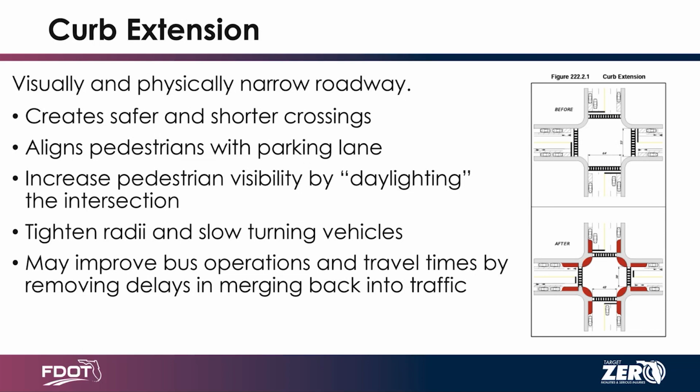And then you're also looking at some of the requirements in the MUTCD around all-red times, making sure that you're accommodating, especially when there's a bicycle signal. But if you think about it, if bicycles exist anyway, we should be doing it: extending the all-red time to account for the extra time it takes for a bicycle to clear the intersection. So when you start looking at these massive intersections, not only is it safer to keep it smaller, but there are some efficiencies that you can get as well by making smaller intersections.